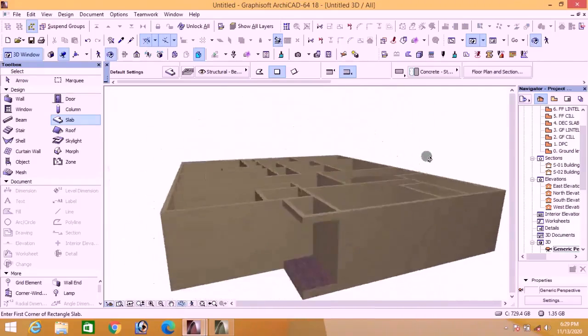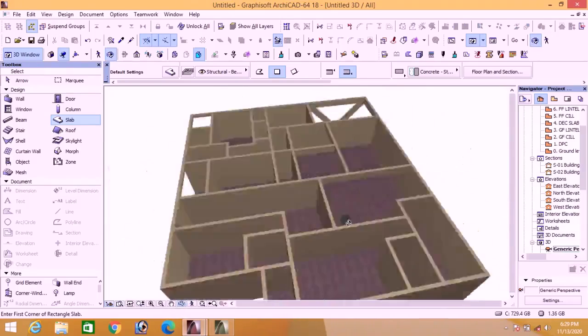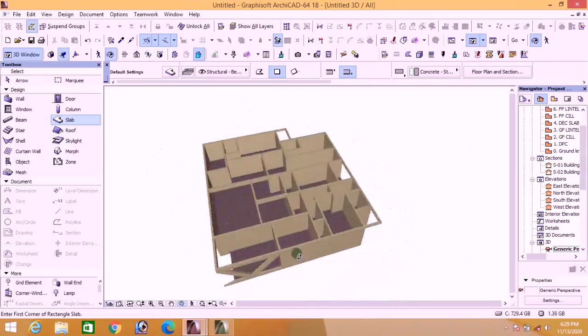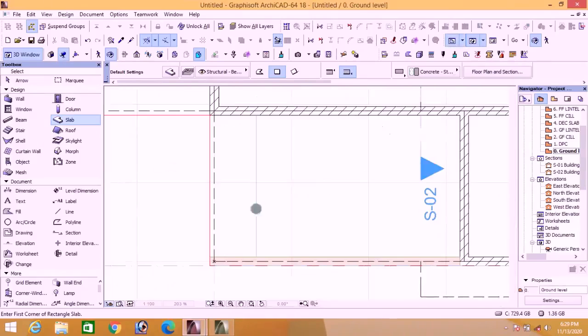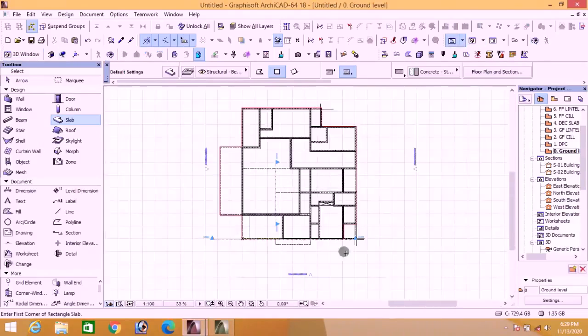So where other place do we have to put our slab? We have done that of the kitchen. So now the next thing we do is we install doors in this building. Let's go to our floor plan. Now to install door in this building, you don't do it at this level. You go to your DPC. That is where you install door. Click on DPC. DPC will open.